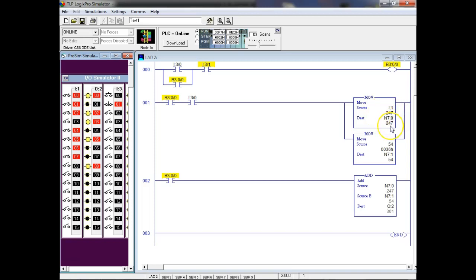All you're going to do is, but I'm going to have the ability to do what? Change these numbers. And that's what's nice about using the move. You could use immediate addressing on all of them, but if I wanted them to see something different, I would have to go back and do what? Change all these instructions. Here I can just come in and change these two numbers. And then next time we load it, or tell it to add it, then it'll do something different. Are we okay?